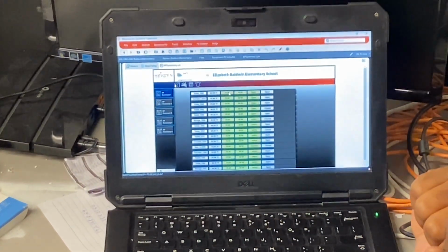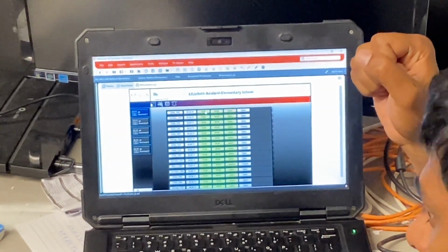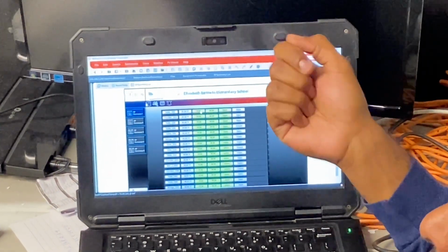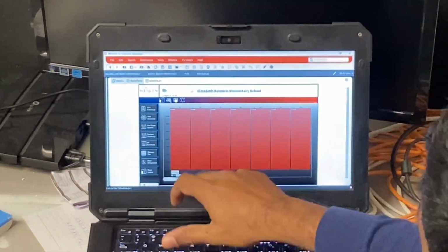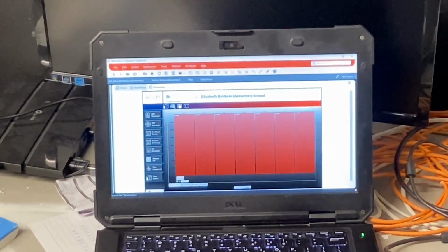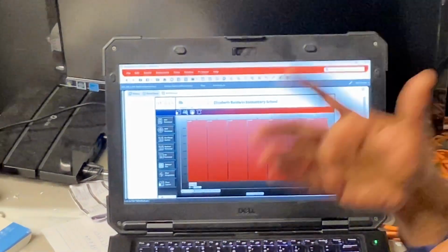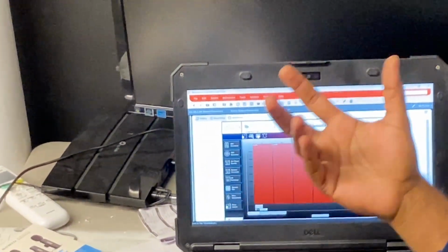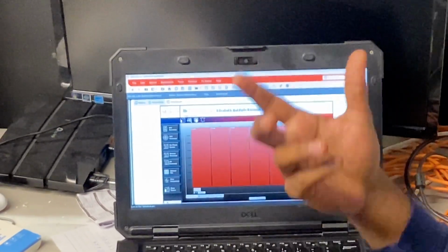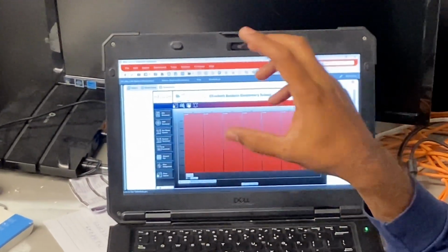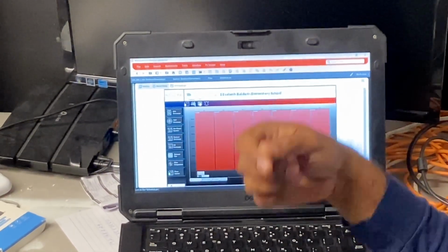The other thing I forgot to mention when we talked about VAV is that you can override the occupancy. Basically you can set the schedule. Right now we are in flush mode, so it's all 24/7, but you can set whatever schedule you need. But if some people are coming here, let's say for an event on Saturday, Sunday, or after working hours, there is an occupancy override button on the thermostat which you can click to put it in bypass, which is basically occupied for 2 hours.